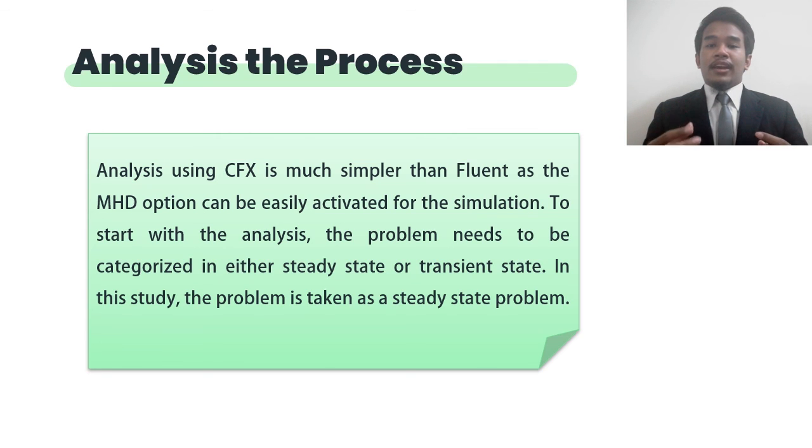Analysis using CFX is much simpler than Fluent, as the MHD option can be easily activated for the simulation. To start with the analysis, the problem needs to be categorized as either steady state or transient state.